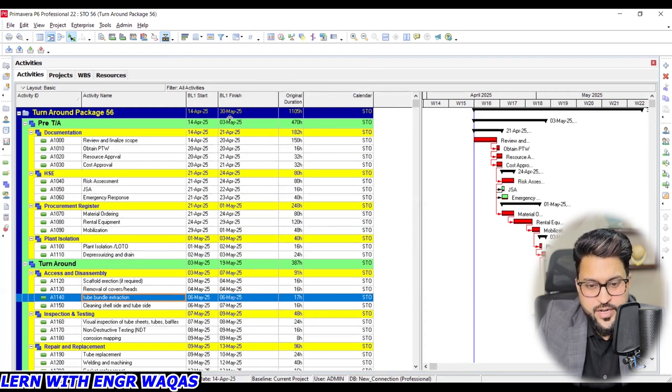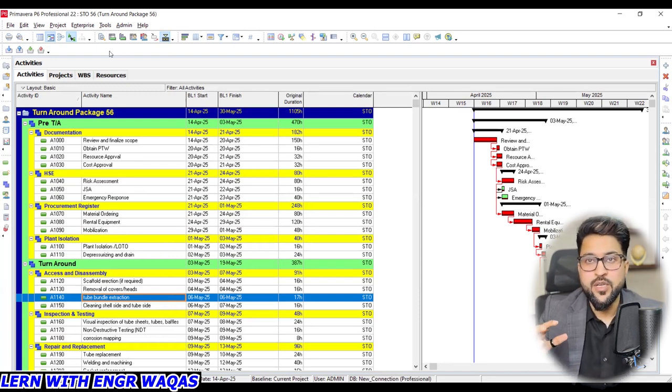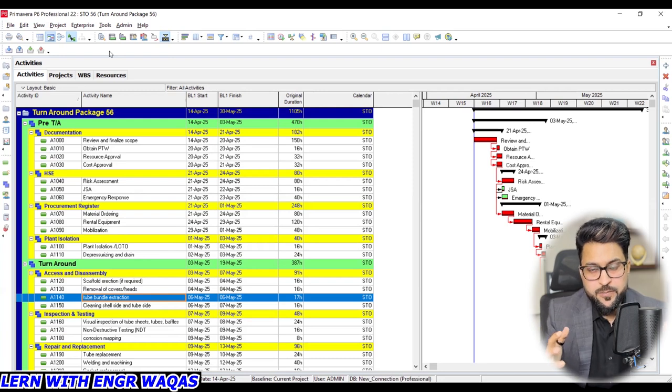You understand now? This is again going on 30 May due to some kind of interventions during scheduling and all that. This is our critical path method. So, what is critical path method? Critical path method is actually when you are going to assign relationships, when you are going to allocate durations, relationships, durations, and resource availability is going to develop your project critical path method. Critical path method is your project longest path strategy, which is going to take shortest time to complete that work within that contractual milestone.